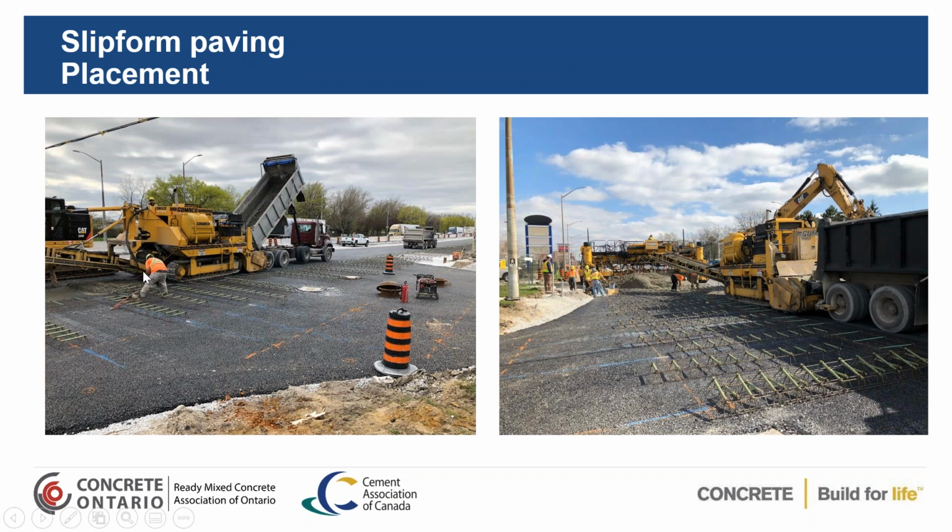And here you see the slipform pavement process. They're getting the side delivery. They're delivering the concrete into a side delivery machine, and then you have your paving machine over here, as you'll see. So this is a very fast process. The dump trucks are coming in, dumping the load, pulling out, and a new dump truck comes in. So you get a continuous flow of material into the slipform paver so they can have a continuous speed and you don't have stopping and starting.